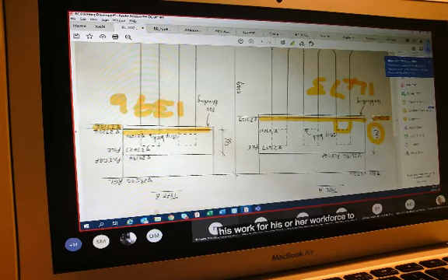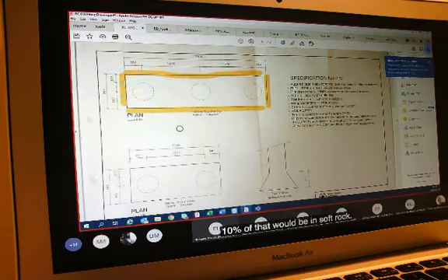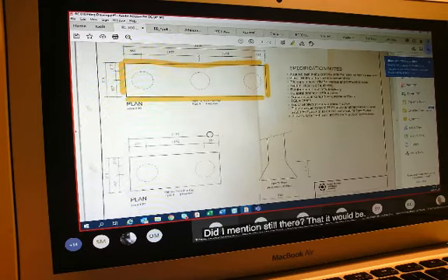So even when we're dealing with working space, what does it mean? Working space means that the contractor is allowing for his or her workforce to be able to safely work in that area, and we need to ensure that it is allowed for. So we include that when we say extra over back excavation for working space for excavation in soft rock, we say times 10%, and ditto but in hard rock.